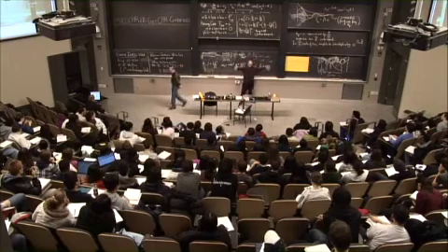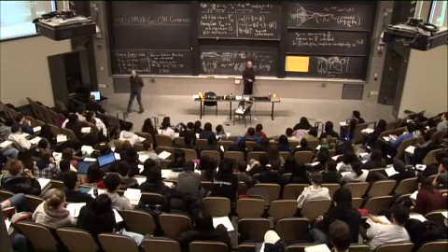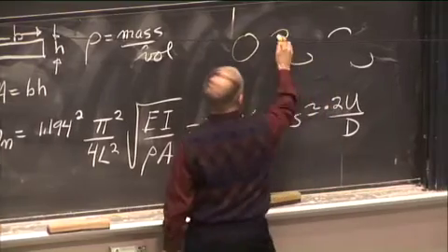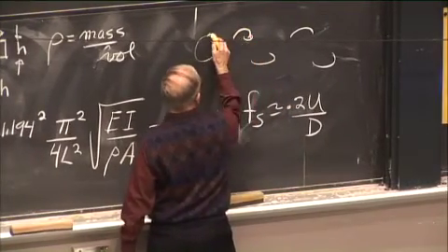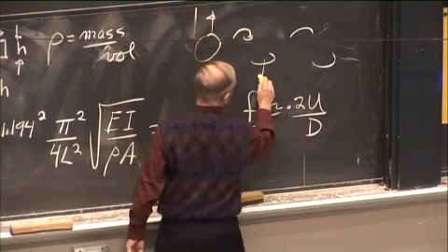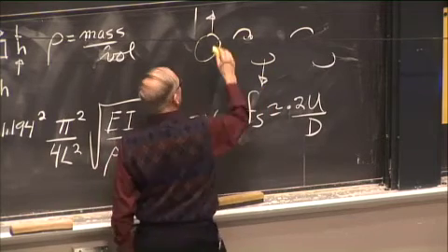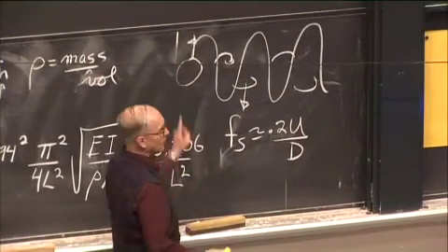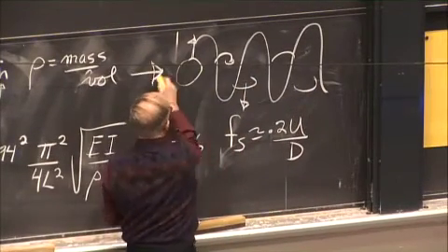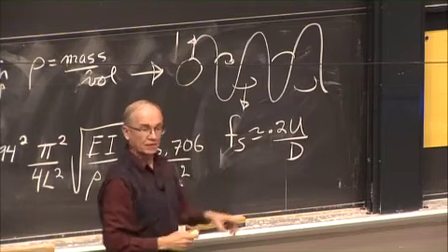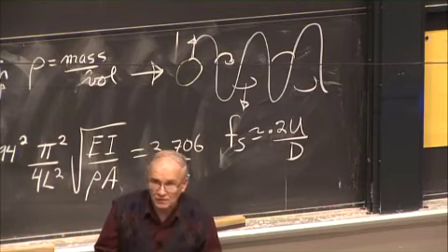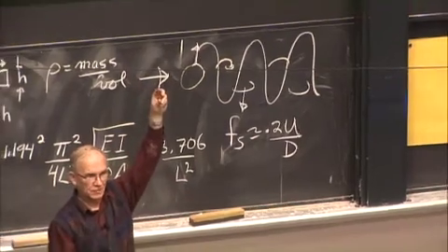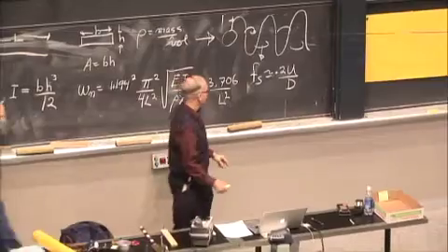So something this big around with a current of 1 meter per second going by it will have vortices shed at 0.2 hertz. And every time this vortex is shed, you get a force upwards, and on the other half cycle, you get a force downwards. It causes a periodic force on the cylinder transverse to the flow. The flow's coming like this, the force is this way. And if that force is near a natural frequency of that string, what'll happen? It will oscillate. So we're going to show you an example of that.